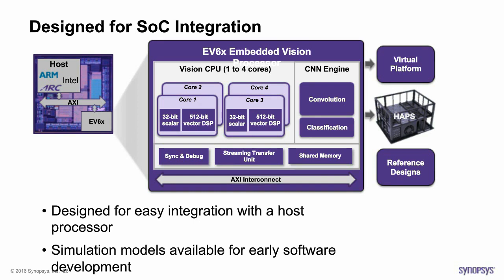And as you know, a GPU could be used for the vision processing, but what we're seeing is a trend to build in a separate vision processor, which sounds a little bit self-serving, but when you think about it, it makes a lot of sense because the GPU, while it's capable of doing the vision processing because it has a lot of DSPs, typically would be used for other things, so there's probably not a lot of spare cycles to do the vision processing, which takes a lot of horsepower.